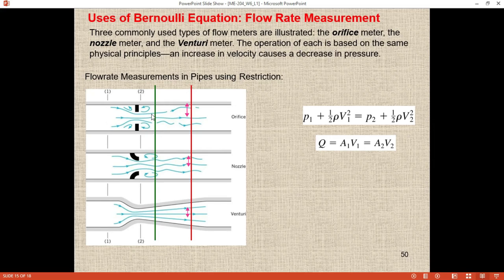The boiling temperature is reduced. If the boiling temperature is reduced, what happens? There is vaporization. This vaporization basically causes cavitation. So here you can see the cavitation space. Okay, so if you have a sensor here, you will not get a right reading. You will get some reading, but it will not be accurate, appropriate, or trustable.